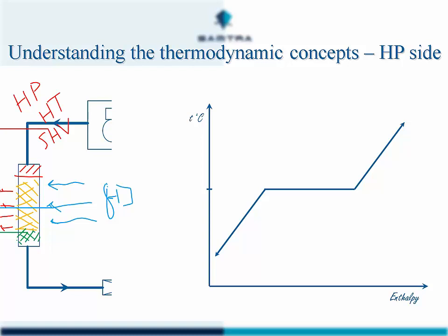So the refrigerant leaves the condenser. It is still on the high pressure side. Okay, it is still high pressure, high temperature, and we now know that it should be a subcooled liquid. Okay, and that's what's arriving at the expansion valve. So the compressor is only handling superheated vapor. That's all the compressor wants. Liquid coming to the compressor will kill it.